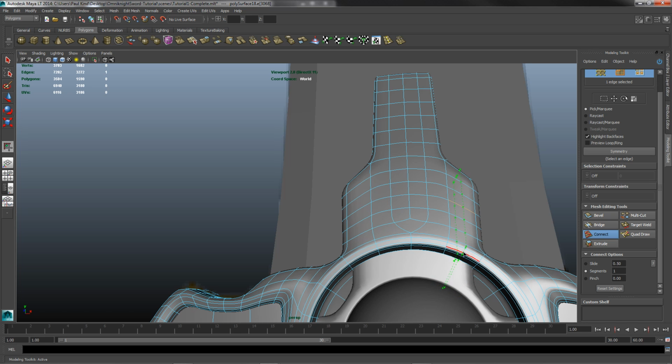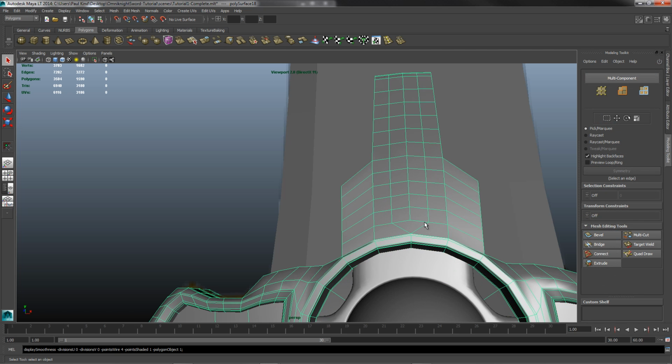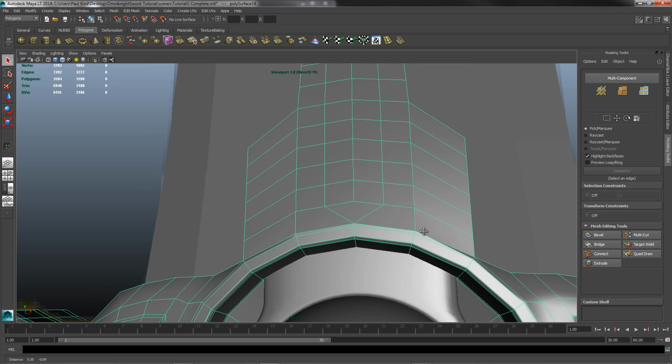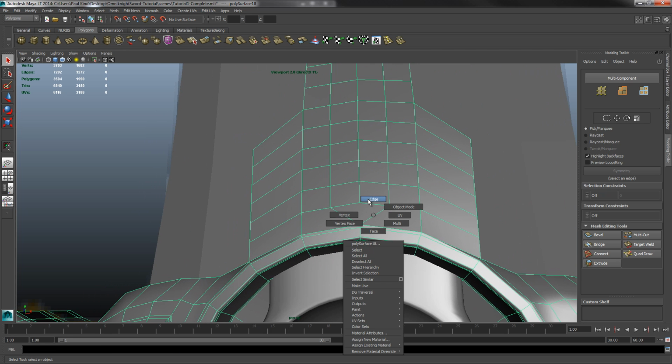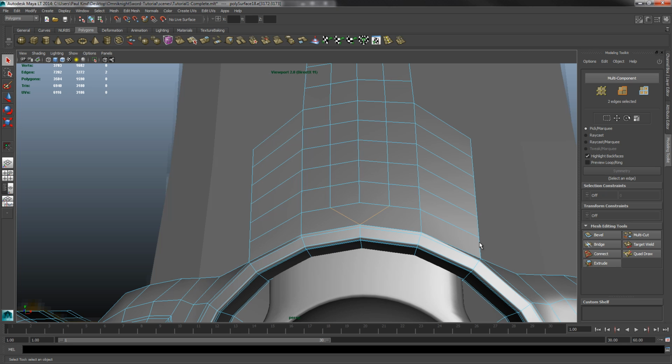But as I said earlier, we never want to interrupt this circle. So to keep the circle perfectly circular, I had to make sure that I didn't have anywhere that it crossed into this. So I put my control loops upwards just to give it a little more control. And then what I did was I just deleted the ones below it, and then connected these ones. And I'm just going to go in here, hit 1, and as you can see, it's just a triangle now. So all I did to do that was I went right-click, edge. I'm just going to delete these guys.